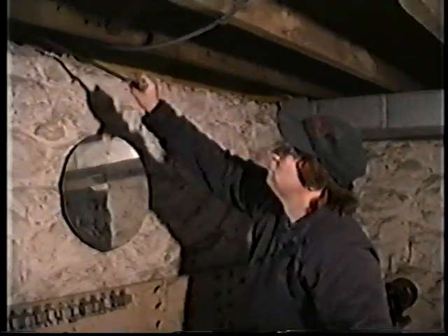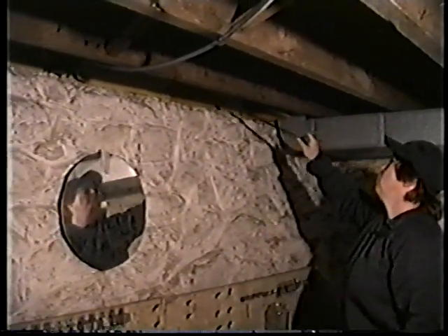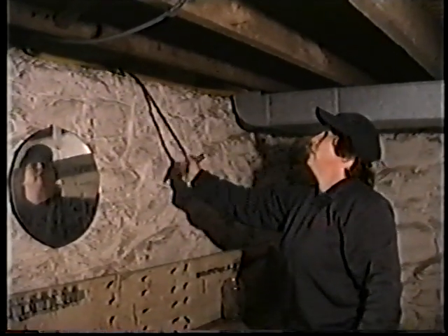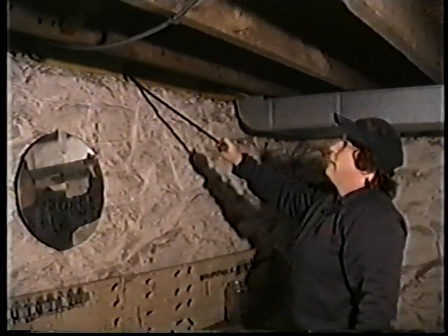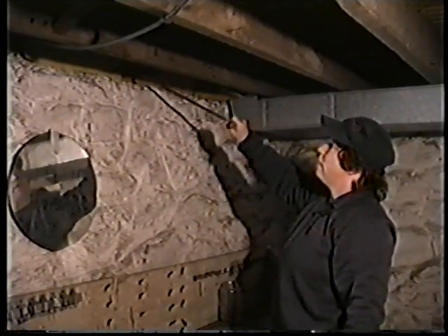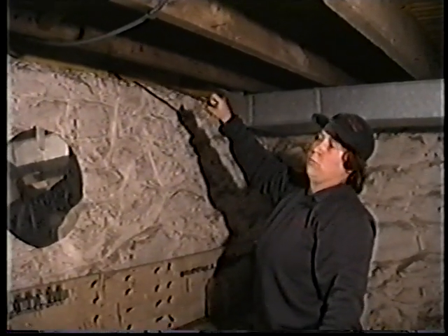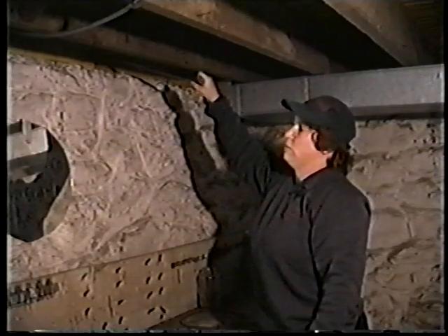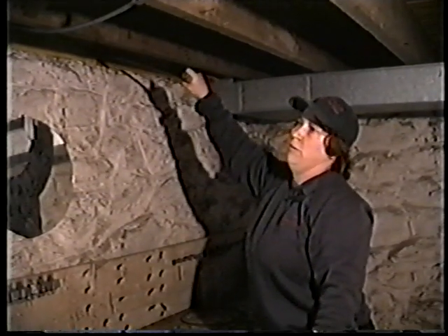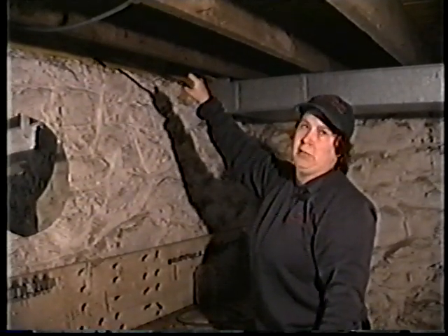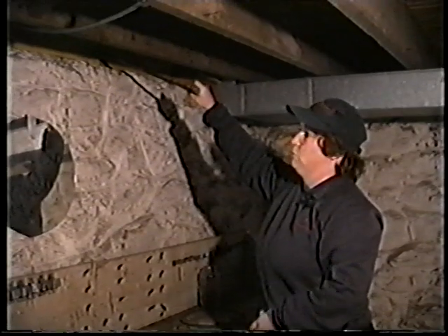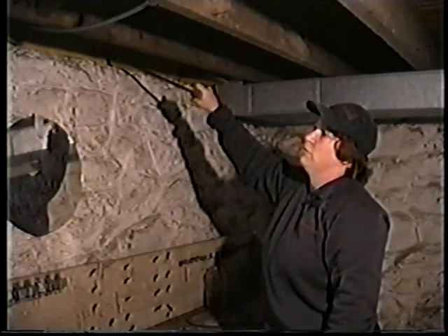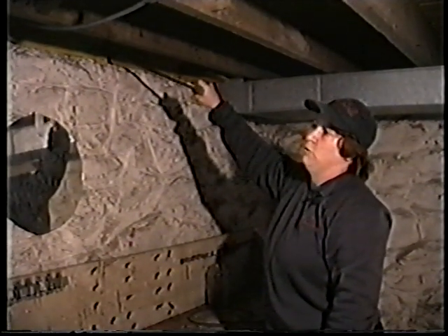And on the inspection report, it's nationwide, it's the same report that we all use. It's the NPCA-1 form. There's a spot to say that there was something here, so that we're all working off the same report. The National Pest Control Association made sure that it was simple to understand and read for everybody, and it protected both the companies doing it as well as the buyers. Because what we're looking for is any evidence of wood-destroying insects.